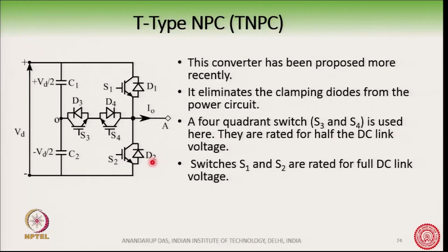Now, the difference of this TNPC from the conventional NPC is that we have only one switch here. Okay. And there are no clamping diodes. Instead of the clamping diodes, we have these 2 switches. Now, remember what are the ratings of these switches here?